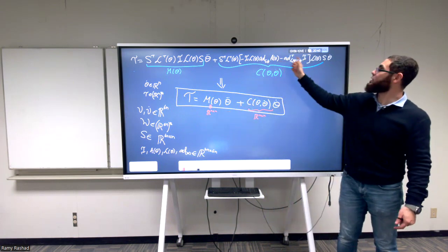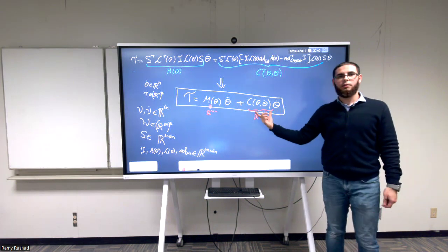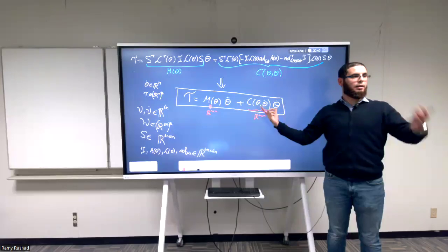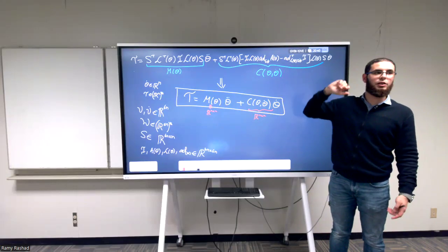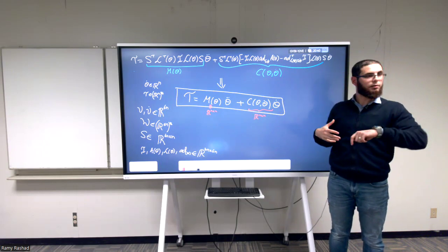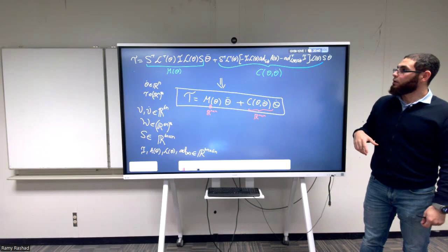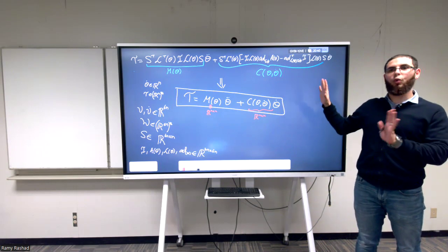The same also here. You see here we had some Coriolis term, some gyroscopic term, and this is why in the literature this is called the Coriolis and gyroscopic matrix, because again it comes from all of the expressions that we had on top, and of course the cross coupling between all of these bodies together. You don't write this on paper. I just wanted to show you once in your life.